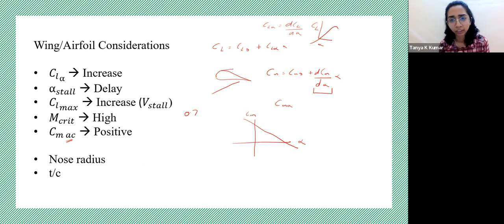Yes, you're absolutely right. Just a few corrections in the terminology. It's nose up and nose down, pitch up, pitch down. You mentioned it's the entire aircraft. He's absolutely right. So you need it to produce a countering moment so that it returns to, or at least has a tendency to return to, equilibrium, which is why you need your Cm alpha to be negative. That is, for a positive disturbance in alpha, you need a negative restoring moment. That's why your Cm alpha should be negative.